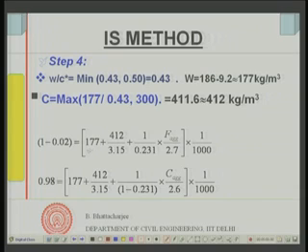this is the amount of water divided by 1000, obviously this is the amount of cement divided by specific gravity of cement, and 1000, because since I am finding out in 1 meter cube, I am taking the total volume as 1 meter cube, cement and water in kg per meter cube. So, everything I am finding out the quantity in 1 meter cube.